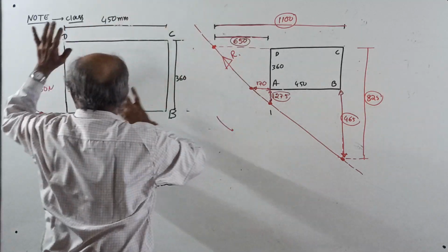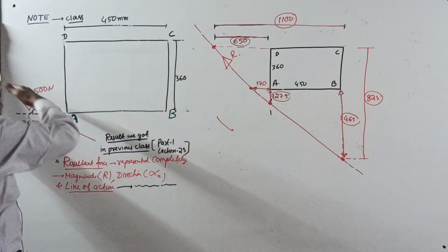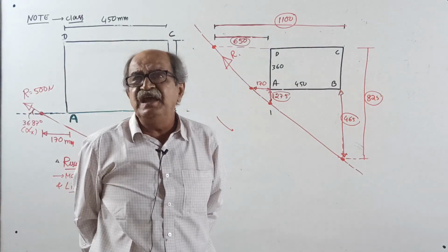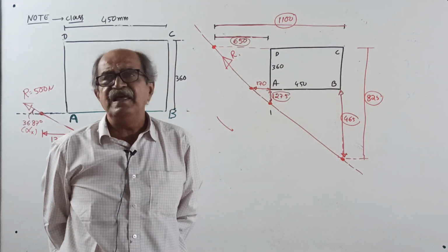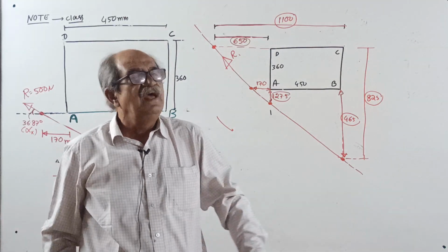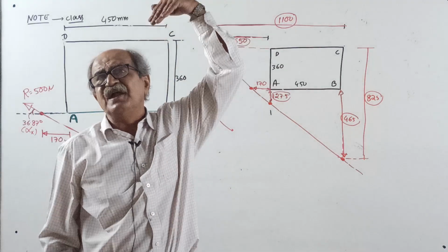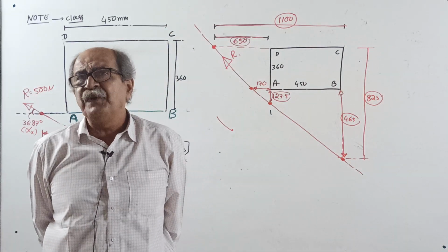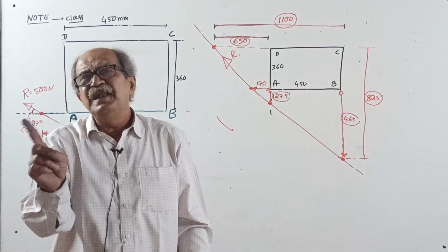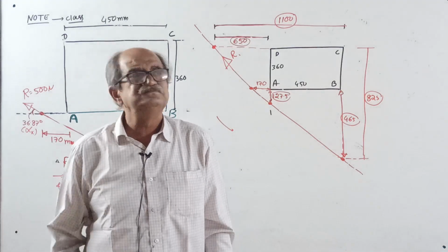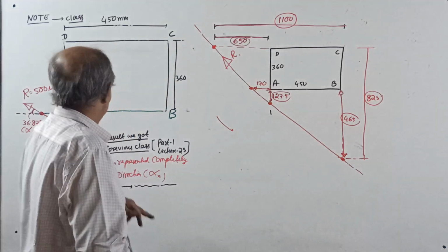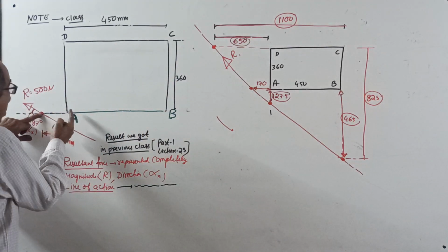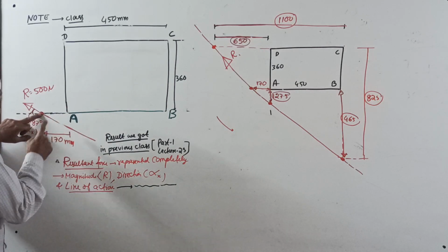The resultant is inclined. So, guaranteed, it will cut each and every horizontal line and each and every vertical line. Along the line of action of a resultant, there are infinite number of points. To define the resultant completely, we need just 1 point. Last time we got that point on the AB line, to the left of A by 170.